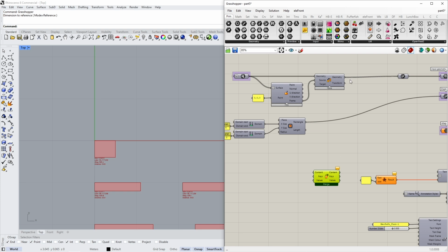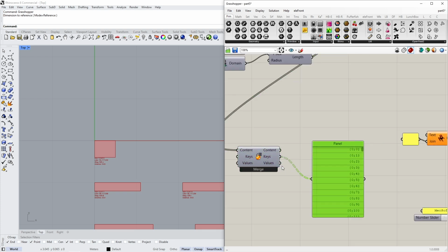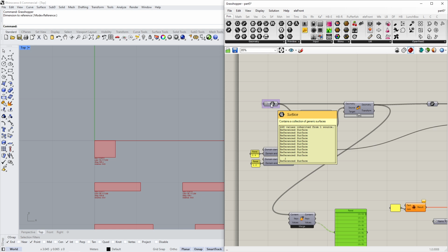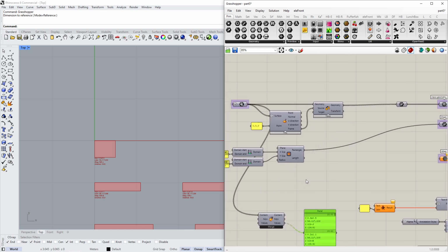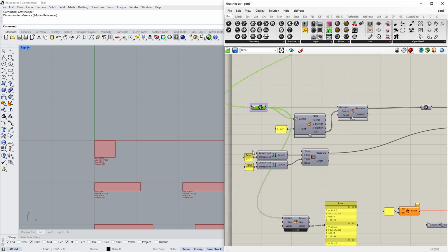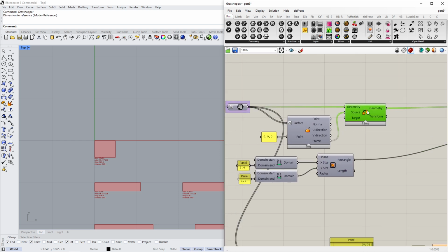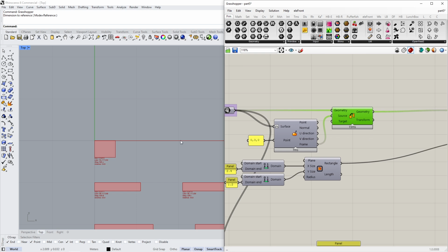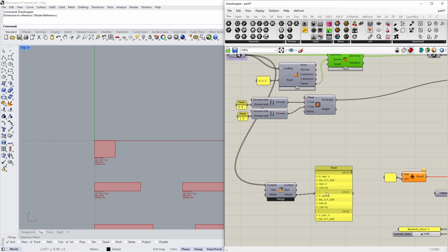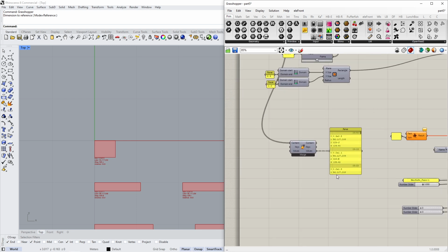And I think from there we can get the key that we want to retrieve. Just see with a panel what the output is. Didn't retrieve it. Maybe from here. Yeah, that's the thing with Grasshopper, that if you do an operation on a geometry, for instance, here we transform that geometry, we orient it on the XY plane, it loses, unfortunately, the key value pair. So I have to retrieve it from the original linked-in geometry.